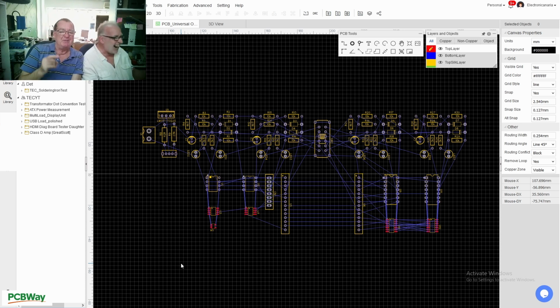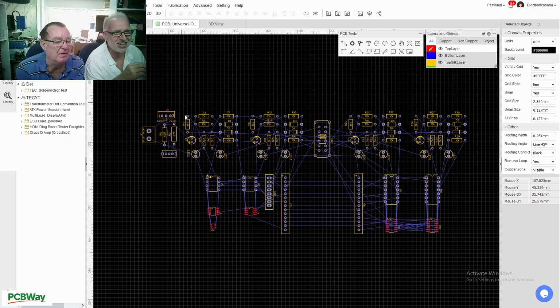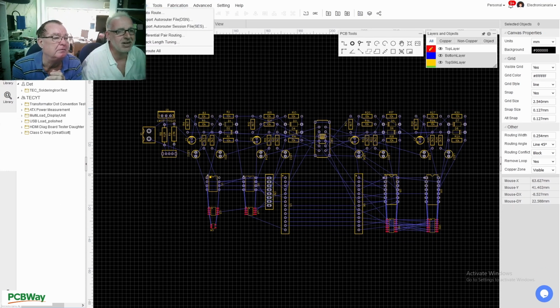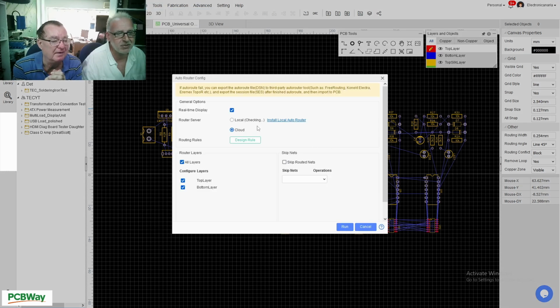Well, I'll tell you what, let's see if Det was right, or due to the considerations I made, I was right. Let's see what the auto router thinks of our PCB. And actually, we can do this before we do the final cleanup, because tracks won't be visible because of the silk screen. So how do we auto route that? Let me see. I think it goes under design or auto route. Yeah, there's auto route. Okay, let's try to figure this out.